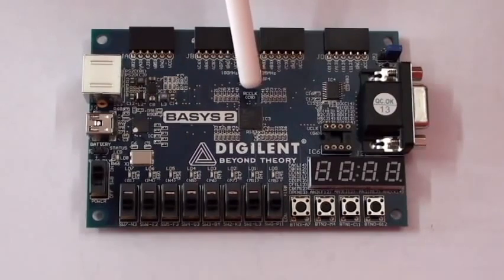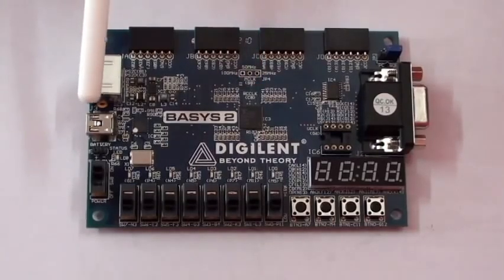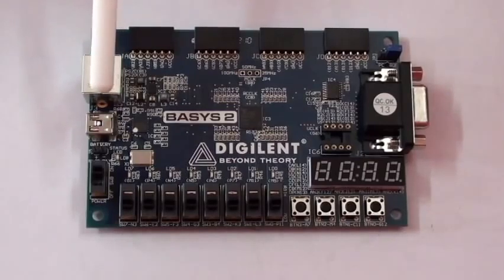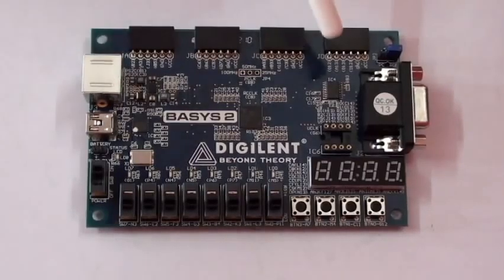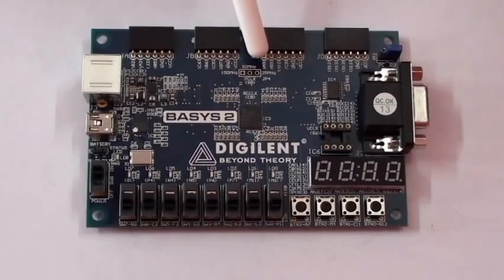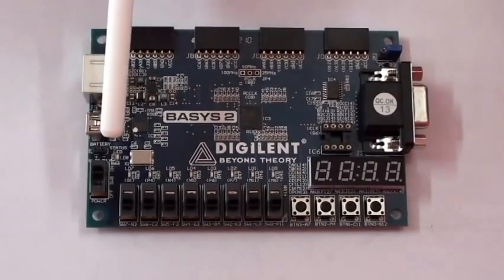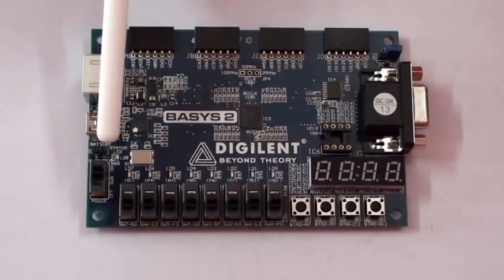This is the core FPGA, Xilinx Spartan 3, which is made up of 250K gates. It consists of 18-bit multipliers, 72 kilobits of fast dual port block RAM, and operates at over 500 MHz. It has USB 2 for FPGA configuration and data transfer, flash ROM that stores FPGA configurations, a user settable oscillator frequency of 25, 50 and 100 MHz, and 3 onboard voltage regulators of 1.2 volts, 2.5 volts and 3.3 volts.